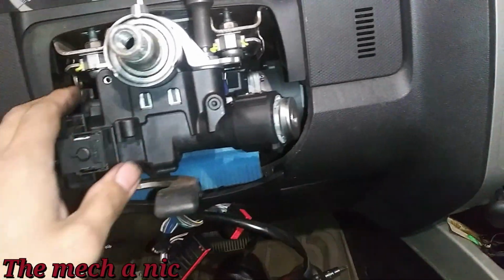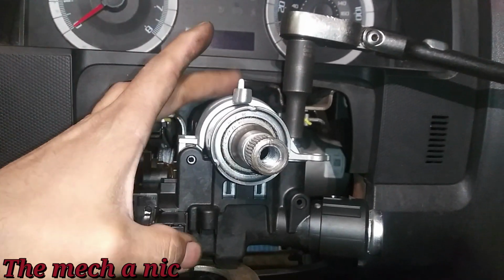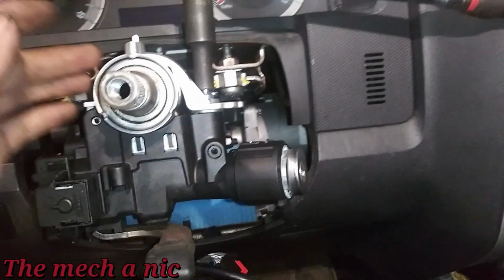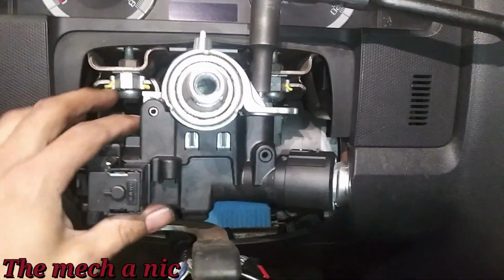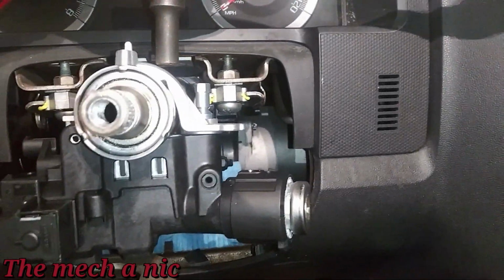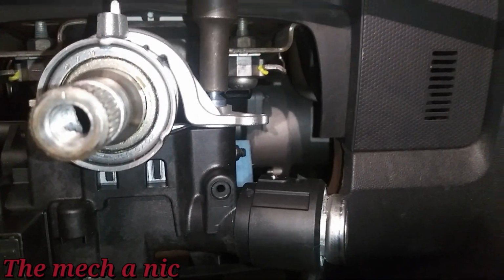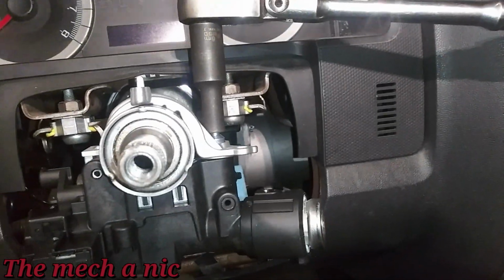Alright, so I got the new piece in. Everything is lined up nicely. There's only really one way this piece is going to fit on here. If it's not lined up correctly, you're not going to be able to close this and get it to latch on to this piece. So it's nice and solid now. The bolt got just a tiny little dab of thread locker on it, and now it's simply go ahead and tighten it until this bolt breaks off.